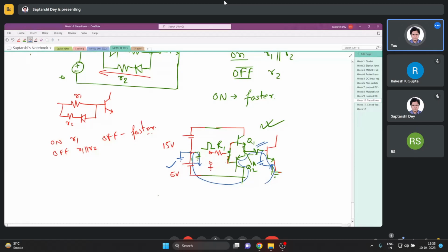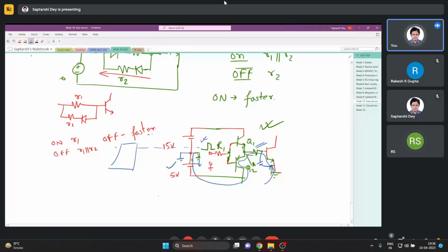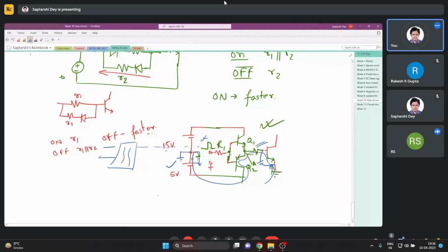So your gate driver ground, gate driver power supply ground, and this signal ground, this has already been isolated from the control. I think you understand it now. So all these grounds must be the same, and the same as the source or emitter of the switch. Okay.